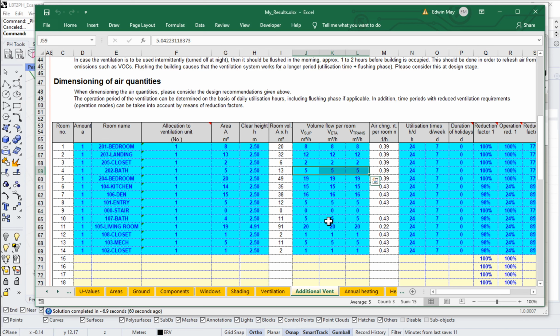So to go back to our PHPP for a second, notice that in the basic approach to ventilation, the typical construction approach, we would supply fresh air to a space, and we would extract air from a space. That's not typical for how we do most of our passive house buildings. Usually we're going to supply air to certain spaces, extract air from different spaces, and then allow for transfer air to carry between them. This is the so-called cascade ventilation approach.